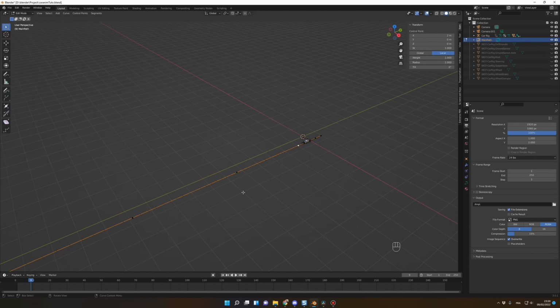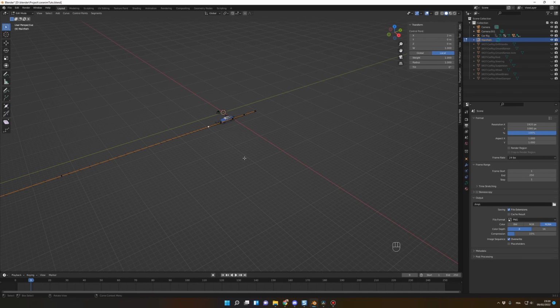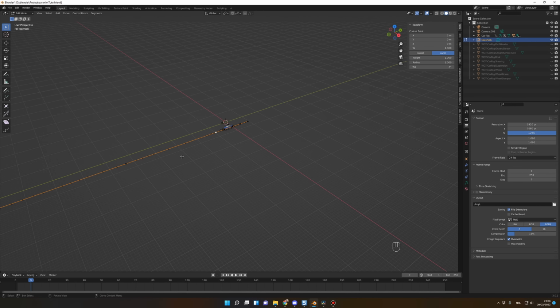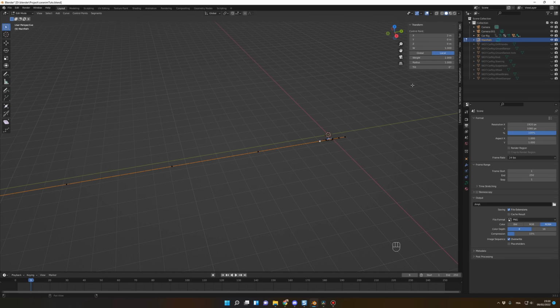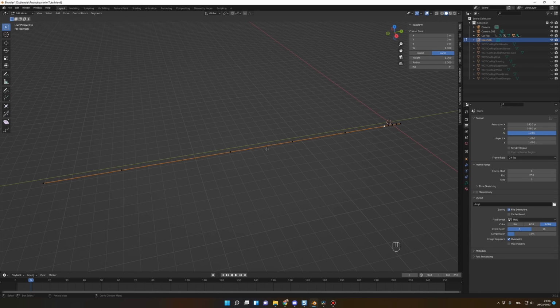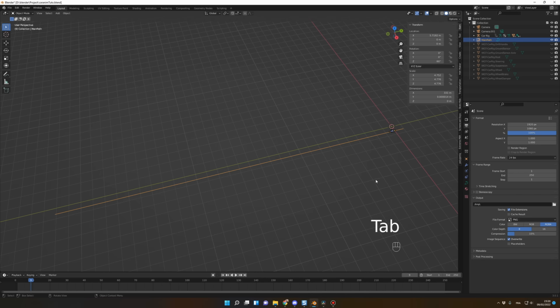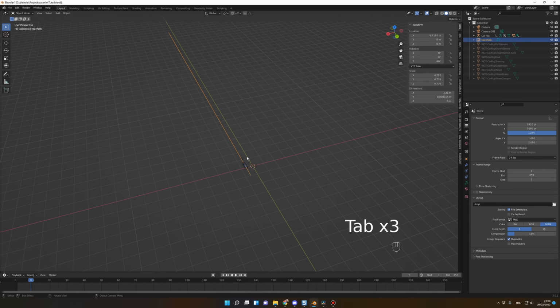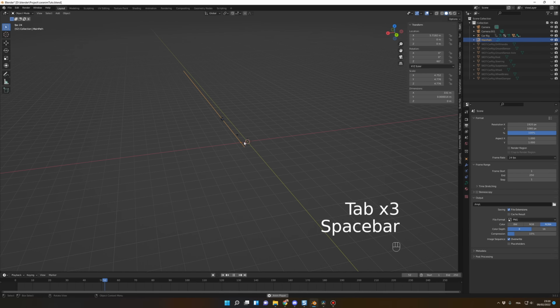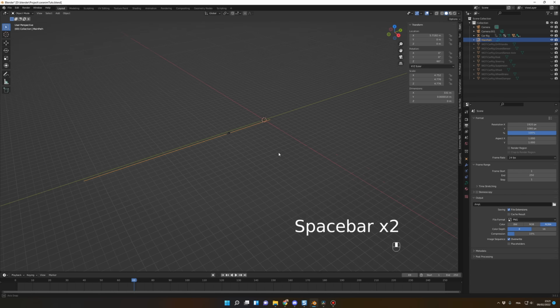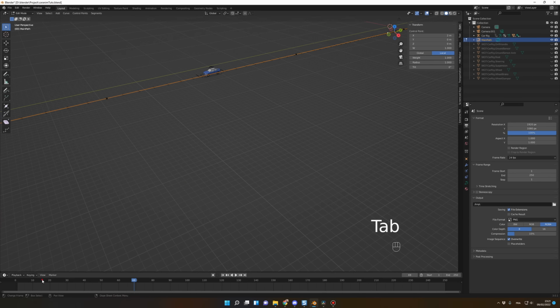So remember, if you have this issue, your car flipping around when you try to add some curves to your path, you should not scale it directly, but you should add some control points using the extrude function in edit mode. Okay, now to make our animation a little bit sexy, because let's be honest, at the moment it's pretty ugly, let's curve our path.